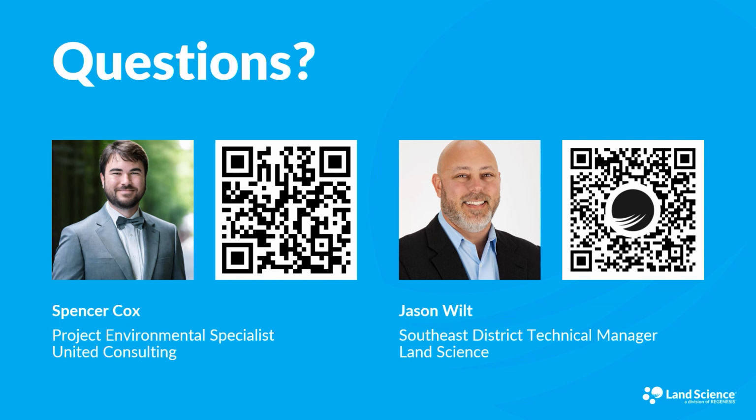Where the hidden costs come in is with active systems, the monitoring that needs to be done to make sure, A, the blower is active all the time, and then B, is it doing what it needs to do to sufficiently pull the vapors from the subsurface through the building to the roof and extracting them. So in a lot of systems, you'll see monitoring that has to occur continuously. You'll see monitoring that has to be done at minimum yearly. A lot of active systems will include an operations, monitoring and maintenance plan that will outline inspection requirements for the building, minimums that the system should be extracting.